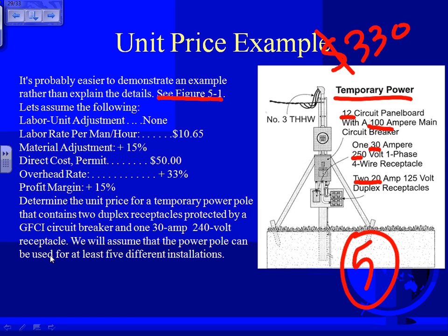Then your labor cost $69, material cost $84. The rig job cost $50 for permit or something. You end up with a prime cost of $203. Overhead $13. Break even $287. I want to add 15% profit on this, believe it or not. I'm reading from the bottom of page 84. And finally, you're going to end up with this baby here, $330. So they did a whole takeoff on one little fixture to come up with $330.